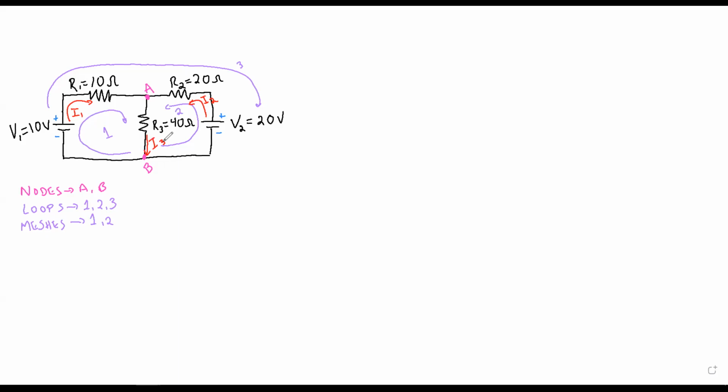The only thing that's going to happen is if the arrows aren't in the correct direction, the result is going to be negative. If I put all of these currents in the correct direction, all of the values are going to be positive. But if one of those currents is going in a direction that isn't correct, then that one is going to be negative. Okay? But the analysis is still going to be correct.